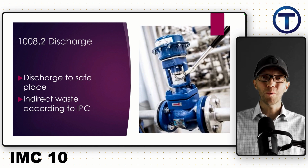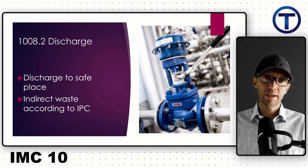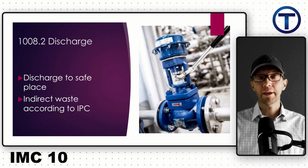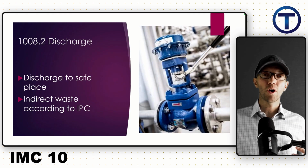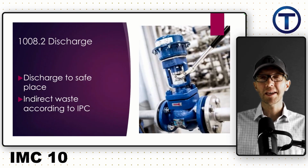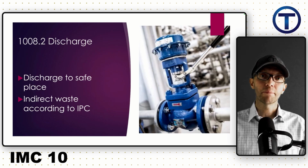Oh, by the way, we probably also should consider the temperature of whatever's blowing out of there. Anything more than 140, according to plumbing code, shouldn't be going down the drain just yet. Let it cool. And I personally don't know how much sediment is coming out of there, but you also probably wouldn't want to put too much of that down the drain, so you might have to be careful about what's coming on the back end of that blow-off valve.